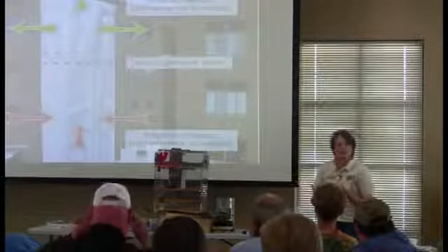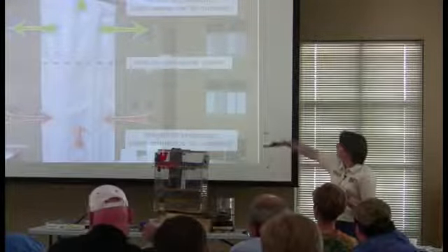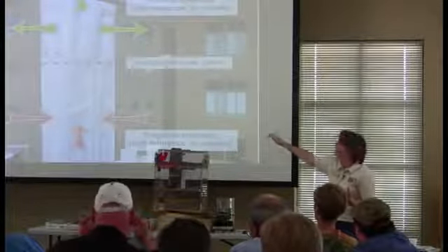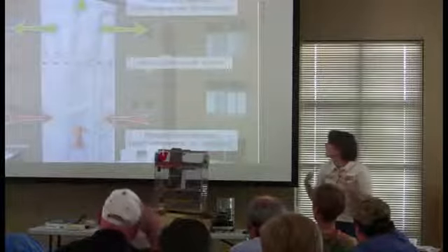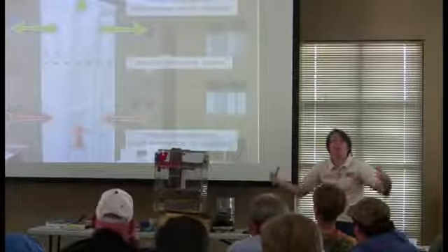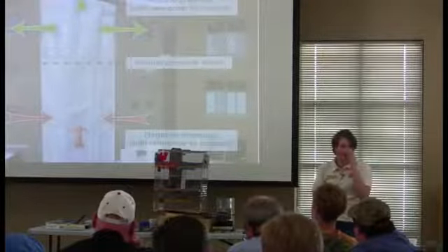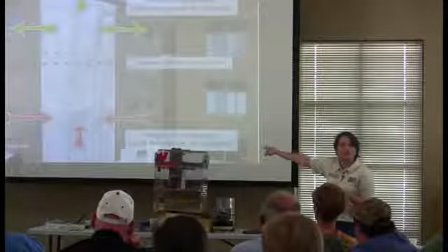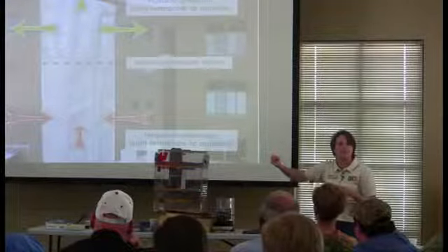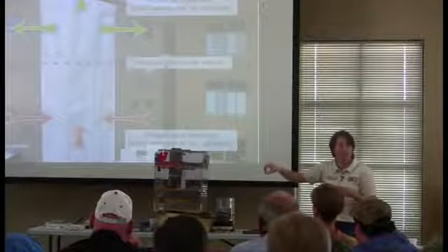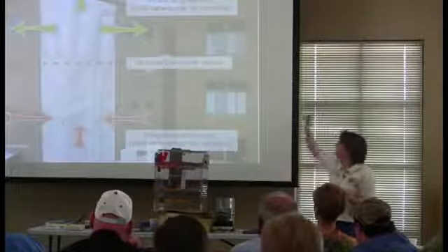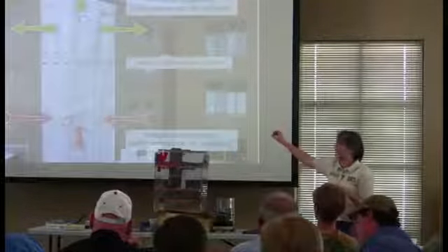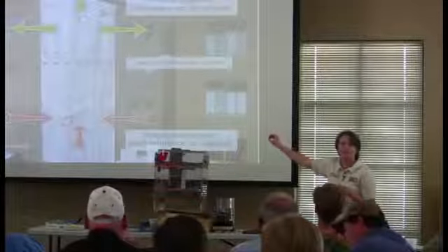You can see that. And then when we move up, we see this place where it's neither out nor in. And then we keep going up, and we get that really big pressure, that really big billowing out. And so what happens if we were to have a hole where the red arrows are? What's happening there? If we had a hole right there, which way would air go? Into the building. All right, if we had a hole in the green arrows, where is it going? Going out.